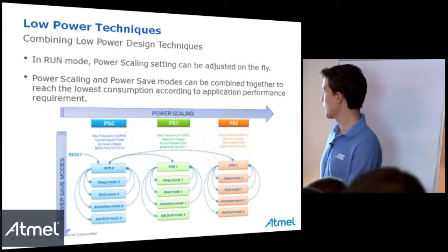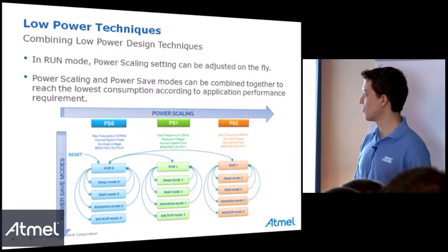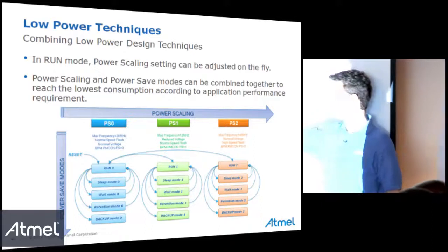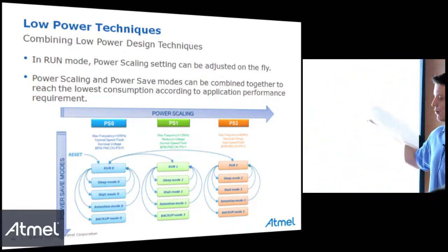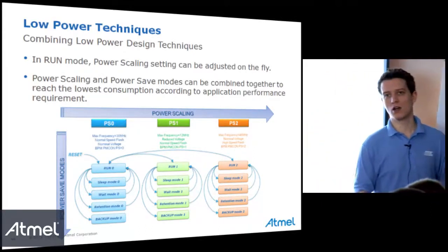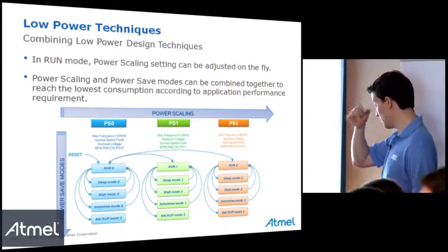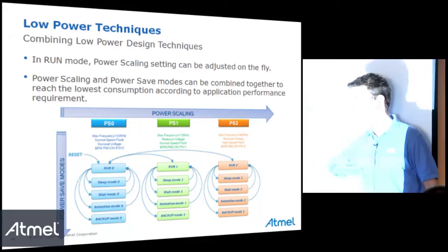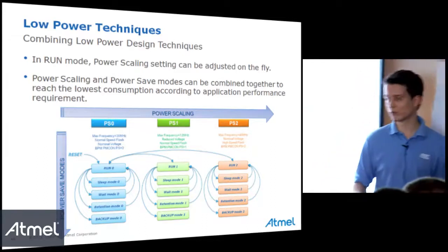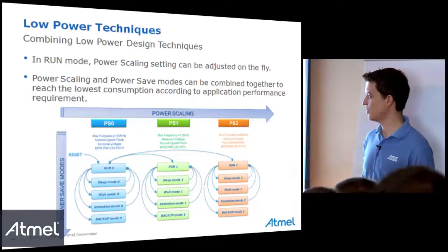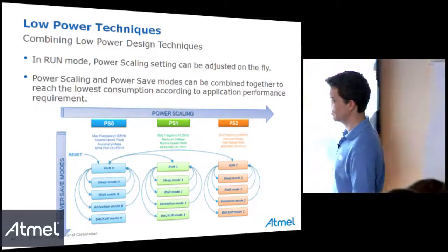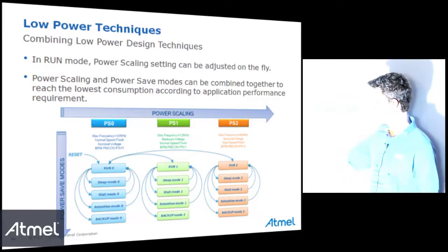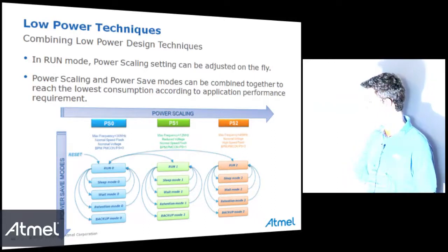No? Okay, just to summarize all the low power techniques. You have three power scaling modes available, which depend on the frequency of your core. In each of these modes, you have the sleep mode or the wait mode, all the low power modes available. So in a concrete application, usually you will go after a reset into this mode. This is power scaling 0. Then you can go into low power mode.